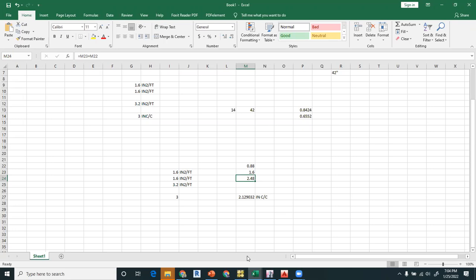I will recommend to all the young or senior engineers: if you are doing design, please do not decrease the spacing of the bars in the raft to less than 6 inches, because there is another serviceability requirement. If the clear spacing between two bars is greater than 6 inches, there will be shrinkage cracks in the raft.